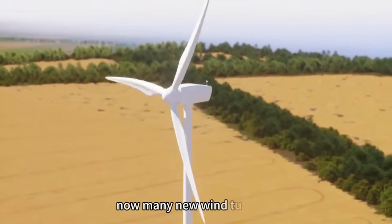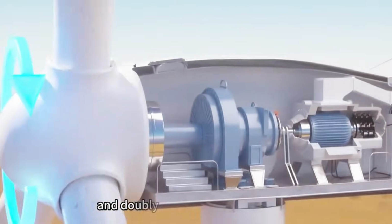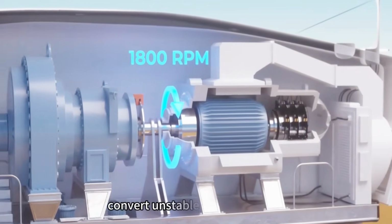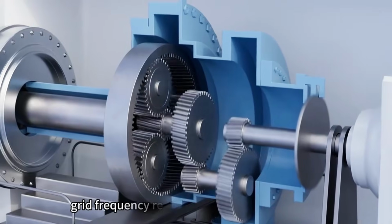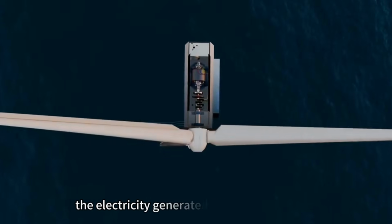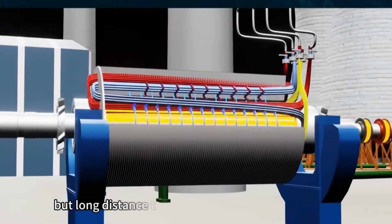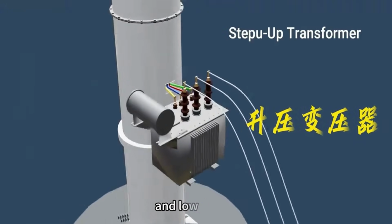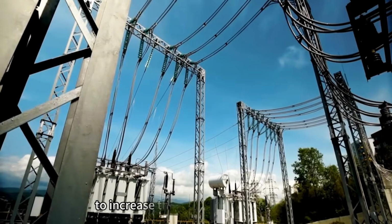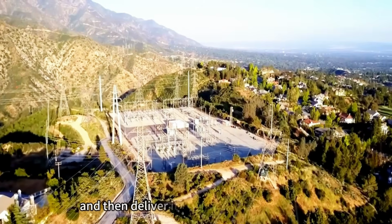Now many new wind turbines have started to use permanent magnet synchronous generators and doubly fed induction generators. Through power electronic systems, they convert unstable speed to stable grid frequency, reducing reliance on gearboxes, and are more efficient. The electricity generated by the wind turbine is generally only a few thousand volts, but long-distance transmission requires high voltage and low loss. So there is a step-up transformer at the bottom of the tower to increase the voltage to 33 kilovolts, and then connect it to the grid, and then deliver to cities and households.